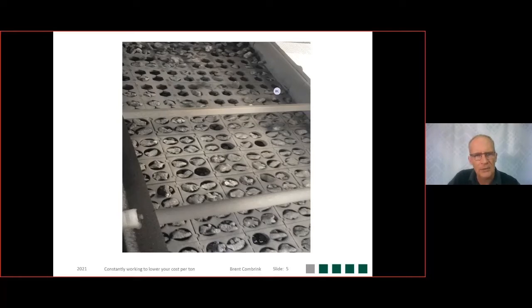Now, why would that be? And the answer is this. The density of that ferrochrome material is almost 3 times the density of the typical sinter material. So the load onto those panels is significantly higher than on this sinter screen. And what happened? The frames actually failed, the panels dished, and that is, if I can show you with my hand, what happens when they dish, they actually bend under load. And that cost Multotec money, and it wasted some of the production time on that plant.